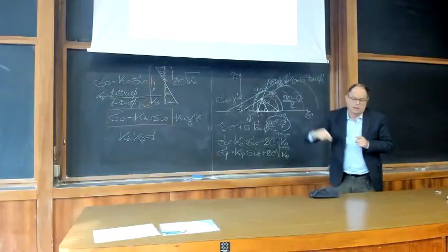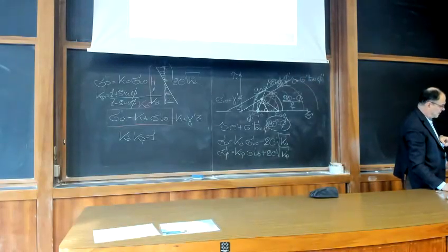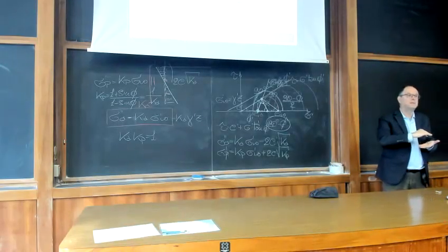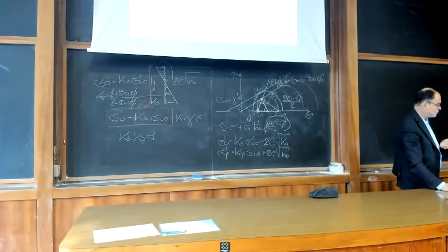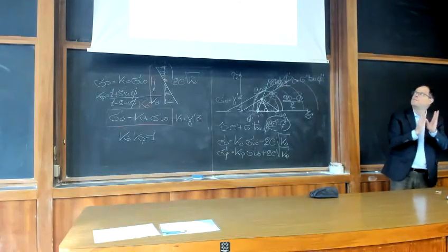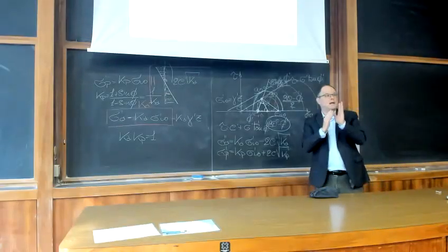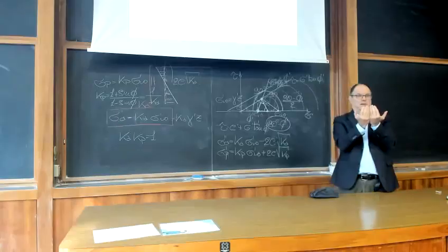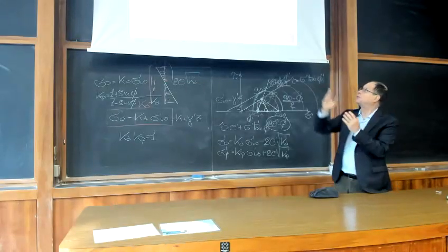Whereas for a deep foundation, a pile, you have both mechanisms acting. You have your stresses transmitted at the tip of the pile, at the base of the pile, but you have as well, and most of the time above all, all the tangential stresses transmitted along the lateral sides of your pile, along the shaft of your foundation.